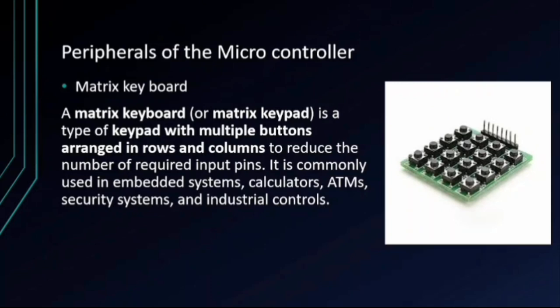It is used to reduce the number of required pins. We have 16 buttons, so instead of using 16 pins, we can reduce them by using 4 and 4, that is 8 pins. It is commonly used in embedded systems for calculation, ATMs, security systems, and industrial controllers.